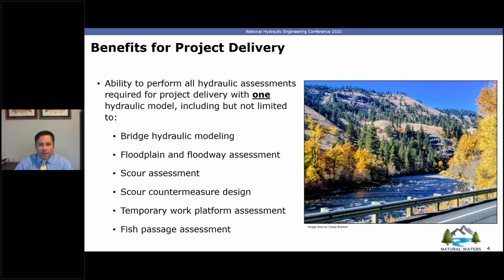One of the benefits of utilizing 2D models for floodplain and floodway assessments is being able to use one hydraulic model for all hydraulic assessments required for project delivery. This includes bridge hydraulic modeling, what we'll be going over today, the floodplain and floodway no-rise assessment, as well as scour assessments, scour countermeasure design, temporary work platform assessments both prior to and during construction, fish passage assessments, etc. Those are just some of the assessments that were utilized for this project.